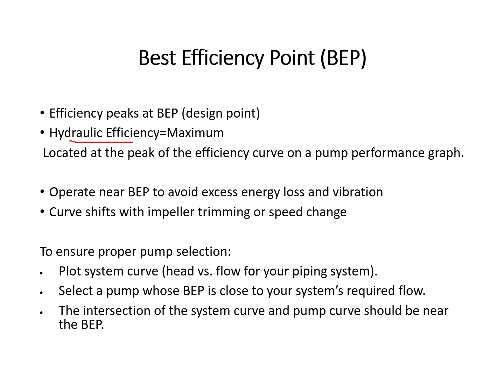To ensure proper pump selection, you have to plot first your system curve, and we'll see how it looks. After you plot your system curve, the system curve is something like this. The system curve. Okay? After plotting the system curve, which is H against flow, select the pump whose best efficiency is close to your system required flow.